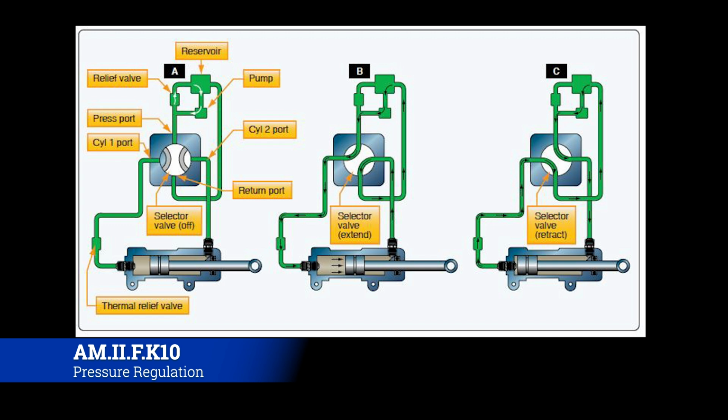Now, one of the simplest examples of this is actually not a hydraulic system, but it is like your fuel control. Like if you're flying in a little GA airplane, you can have your fuel selector on either left, right, or both on most airplanes. That means it's drawing from the left tank, the right tank, or both tanks. What makes that selection possible is a flow control valve. You can either take fuel from just one tank, or from both tanks, or the other tank.